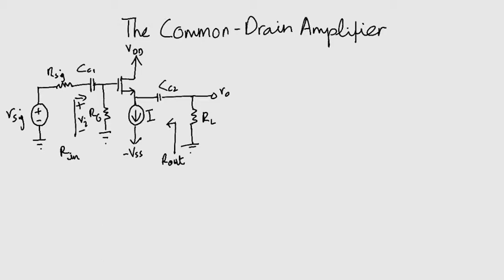Notice that the voltage across an ideal constant DC voltage source such as VDD does not change, and so there will always be a zero voltage signal across a constant DC voltage source. Using this fact, in the small signal analysis, we short the voltage sources. Therefore, we will establish a signal ground at the drain.